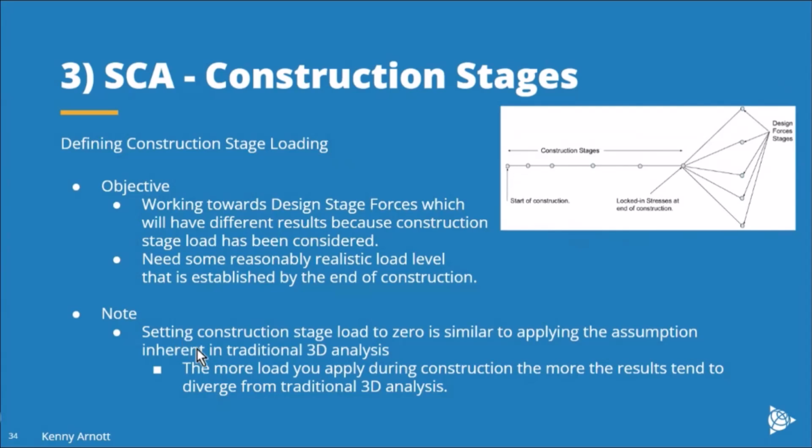A note here: if you were to go through all these construction stages but not apply any load and arrive at this point with a finished model but without any load, and then elevate the load up to design load levels for these design stages, that would just be a long-winded way of actually doing a traditional 3D analysis, because it just kind of skips all of this part anyway. So what makes a difference is how much load you choose to apply during the construction stages.